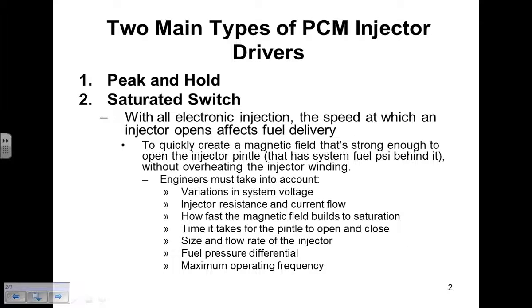All right, so with all injection, the speed at which an injector opens is important to the engineer. When they calculate the fuel map and take all your air measurements from all your sensors, and then design a certain injector that's going to have the right volume with the right fuel pressure behind it, the time the injector takes to open is also something that the engineers have played around with. How fast in time does that electrical injector open? That's kind of where these different designs came from, the peak and hold and saturated switch. And I have some of that listed here.